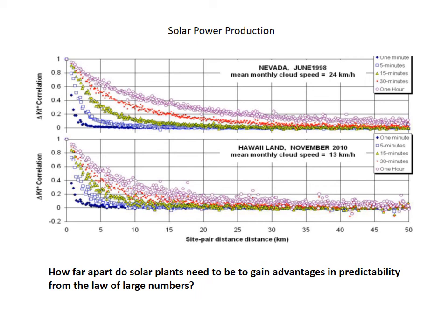So with wind and solar, it's a little tough when you're talking about just building more solar panels or building more wind. It's not guaranteed to give you this benefit, because if you build 200 solar panels right next to each other versus 200 solar panels all separated by a mile, then you're probably going to get more benefits in terms of reducing variability with the ones separated by a mile. Because if they're all right next to each other, whenever it's cloudy, they're all under cloud cover, right?